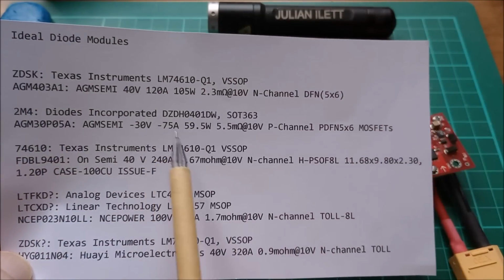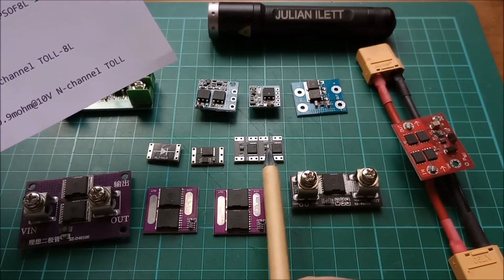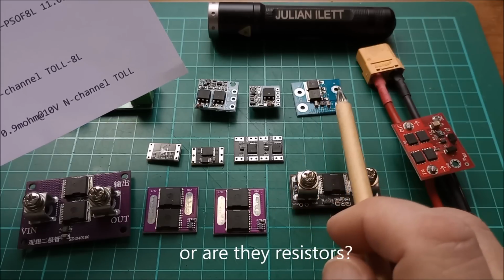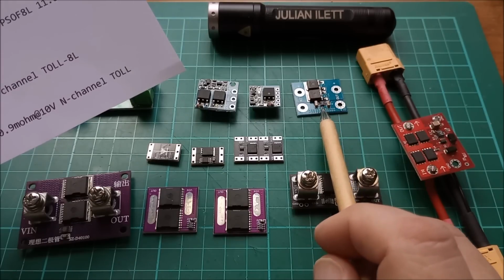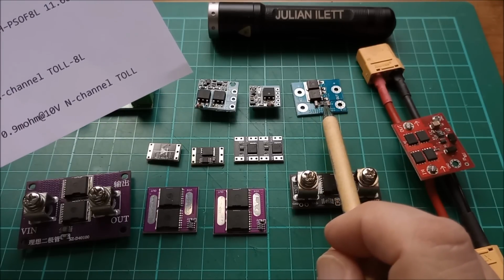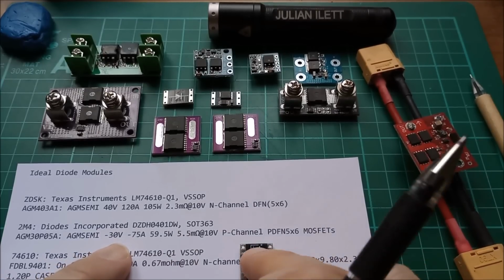Okay, so the second one is using this DZDH0401DW. It's a SOT363. It's very tiny. It's this little chip here, and you can see that it's got these capacitors either side of it, the controller chip and a MOSFET. And this older board here appears to use the same chip. It's got those two capacitors. It's a larger format chip. I think it's a SOT. Yes, I think it's a SOT23. But a lot of these have got their top surfaces scraped off because they don't want you to see what chip they're using. So this second one down is this module here.